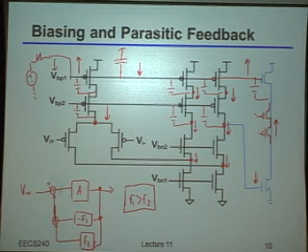By the way, there's a really, really simple solution. Just make that last CS stage driven by a PMOS. Oh, I see. So you wanted to flip over which one was which. So you want to make it so that the gain is actually coming from a PMOS rather than coming from an NMOS. Is that what you're saying? Okay, that is true. You could potentially do that. That works. You have to be careful, of course, with how we bias the NMOS now, because I said nothing about where that came from. But indeed, that's a reasonable thing to do. Any other thoughts? Can you couple that and bias it to something else?